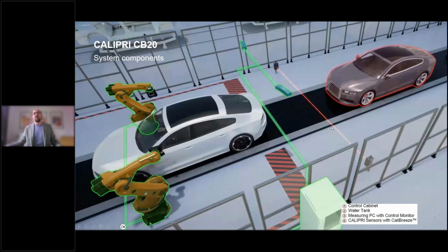There is a secondary sensor to the VPOS, which is a rotary encoder, which will give us the speed of the line, also with latencies of the belt, because the belt is very heavy. It's very full of cars, so we have some latencies in the belt itself, which can be captured by a rotary sensor. Also the 3D cameras will give us rotation, alpha, beta, gamma. So we can always make sure to position our sensors correctly. The offset is of course done automatically.